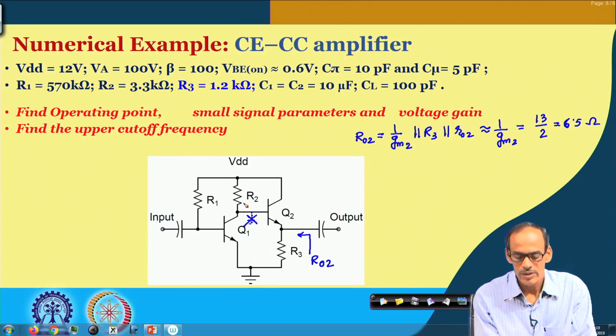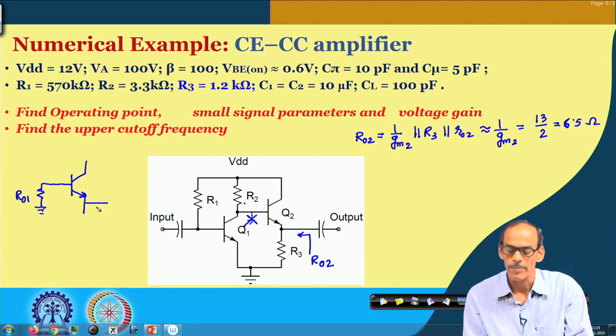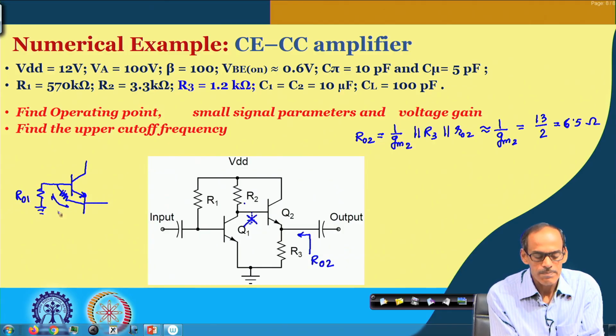But then this is not possible, we cannot do the AC ground here. So, we have to consider the corresponding resistance here. In fact, for the CC stage, we have to consider the resistance at the base, and this resistance is RO1, right. And then we have to see what is the corresponding output resistance we have. That can be obtained by considering the drop that will happen across this R pi in presence of the RO1, while we are stimulating this circuit by say Vx.